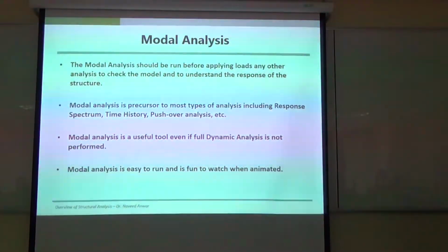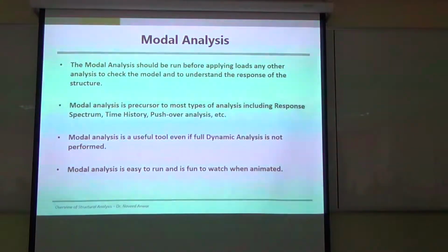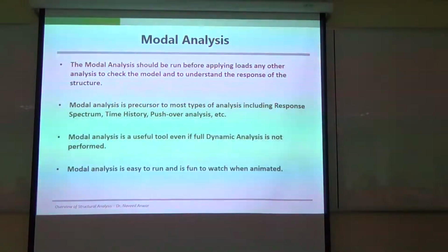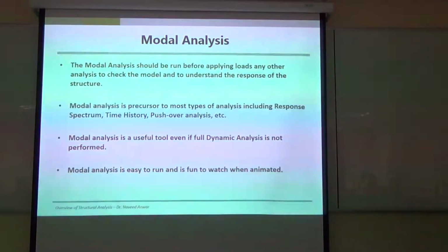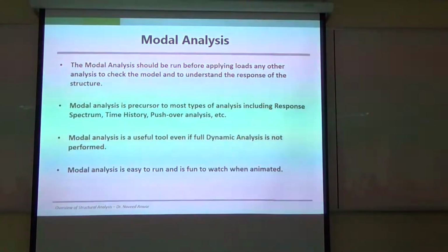When we got the model, I suspected, and when I opened the program, at that time, ETABS used to use steel as a default material. So steel density was the default, which he also applied to concrete columns and beams. So everything in his model became made from steel. So the weight on the foundation was as if it's a steel building, all solid slab with steel, column with steel. So the mass became about 7-8 times more than the real mass, and obviously the foundation became very big.